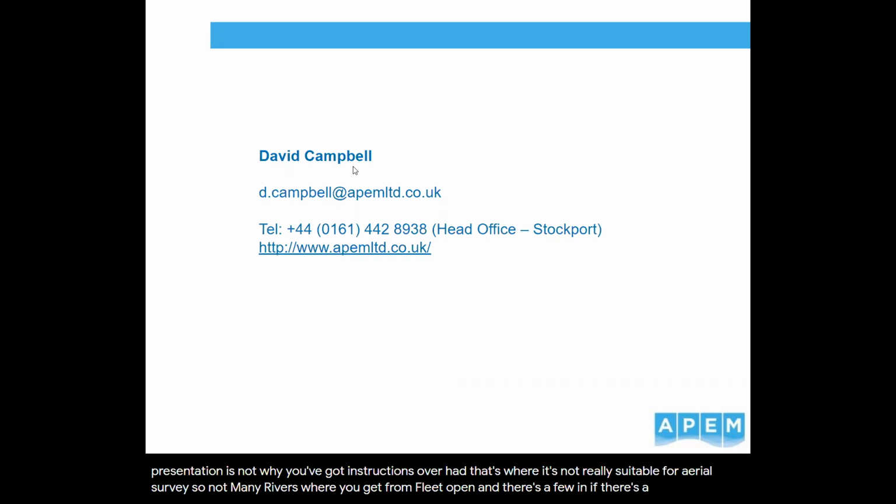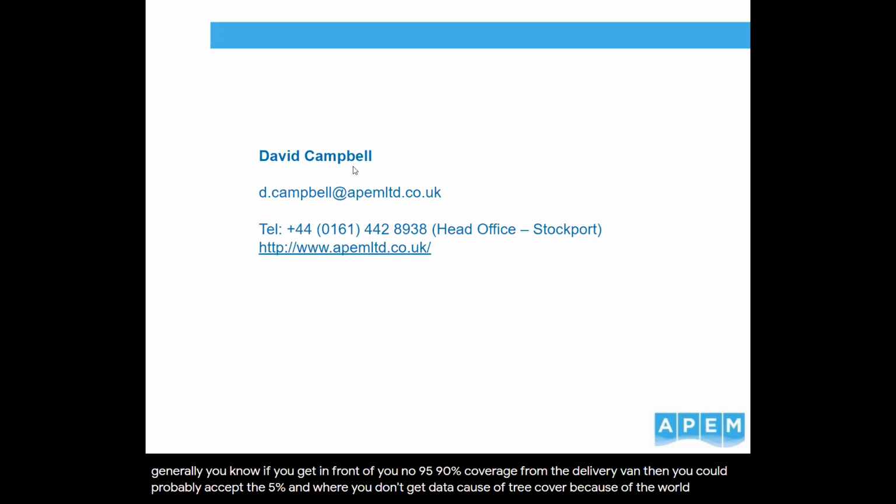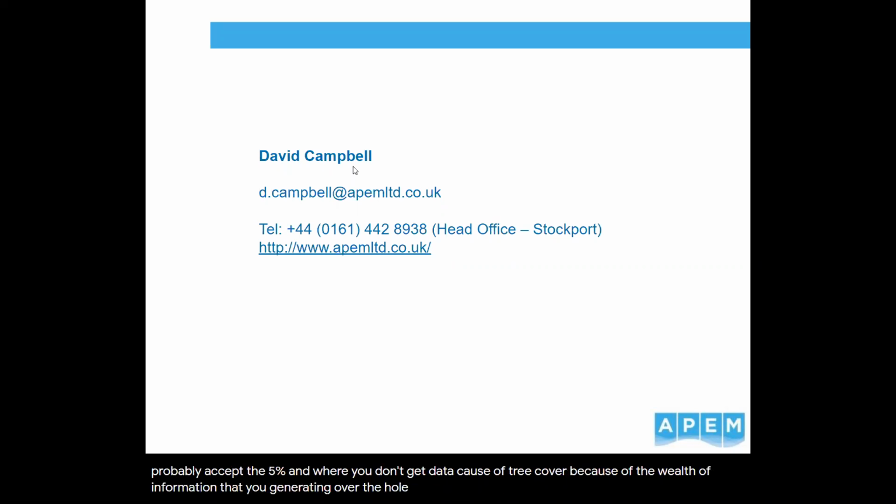And if there's a few trees, then generally, if you get in kind of 95, 90+% coverage from the aerial imagery, then you could probably accept the 5% where you don't get data because of tree cover, because of the wealth of information that you're generating over the whole survey versus perhaps a ground survey. But if you are in a section that's completely wooded, you've got a heavily tree-lined river, then it's the ground techniques that we would recommend for that.